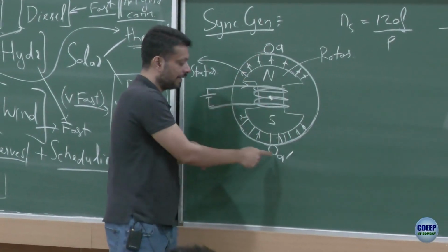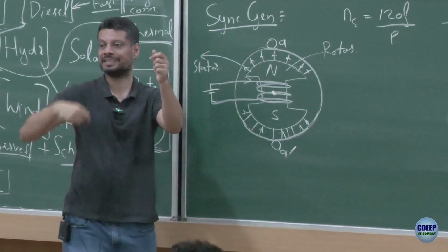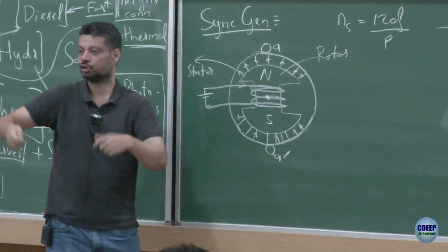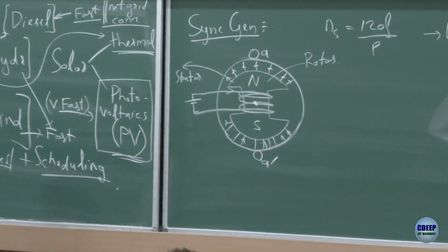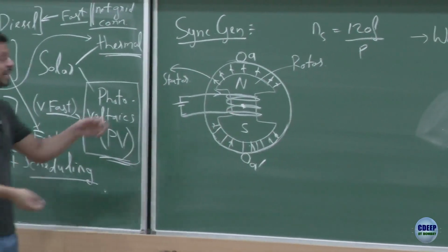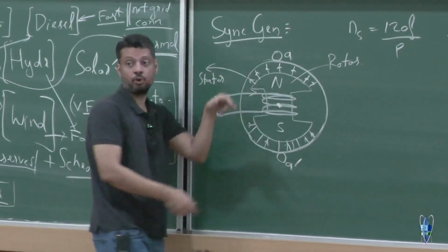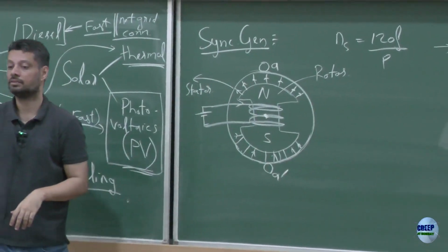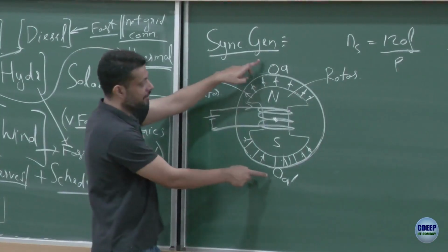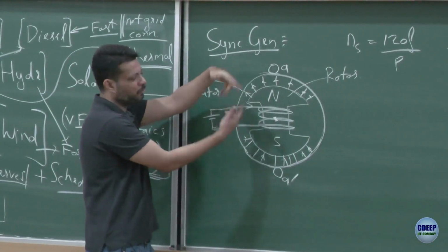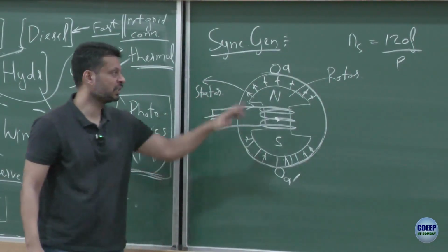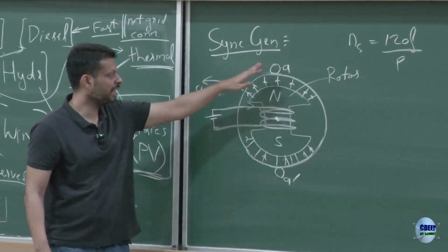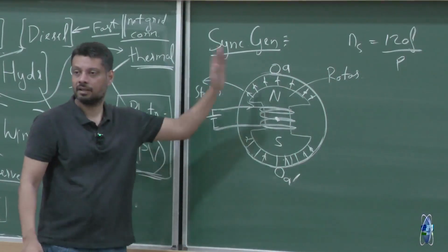And I have a coil here which I have kept open loop, but there are N turns. So this N turn coil would have a voltage induced in it, right? This stator coil AA prime will have a voltage induced into it. For now you just imagine there's just one coil here. Let's assume one turn just to make it simple. There is one wire and that's it, right? So this one turn here, which is going in from here, let's say coming out from here, will have